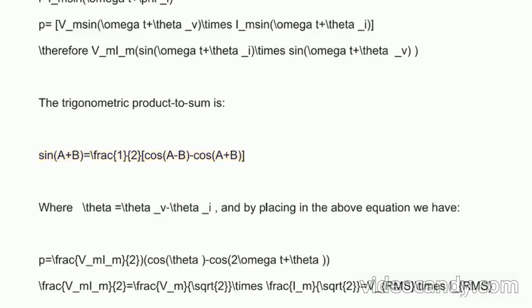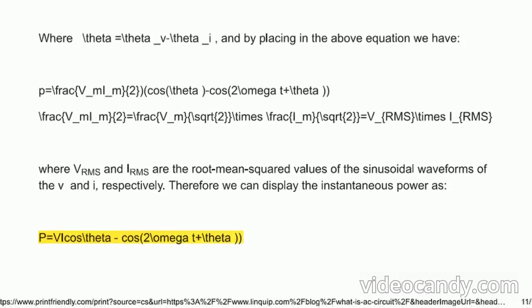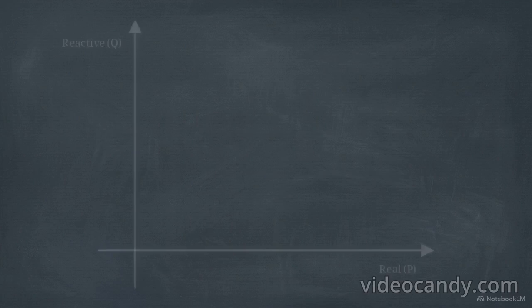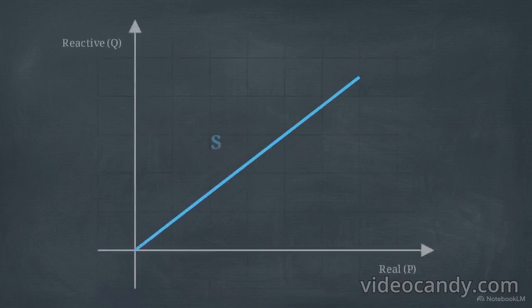While instantaneous power is defined simply as voltage multiplied by current, the phase delays introduced by impedance mean that total circuit power cannot be calculated with a simple scalar multiplication. These trigonometric product-to-sum equations prove that multiplying out-of-phase sinusoids results in two distinct terms. A single phase shift forces the circuit to exhibit two separate power behaviors simultaneously. Watch this power triangle construct on screen.